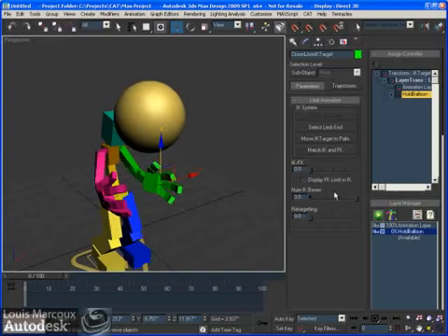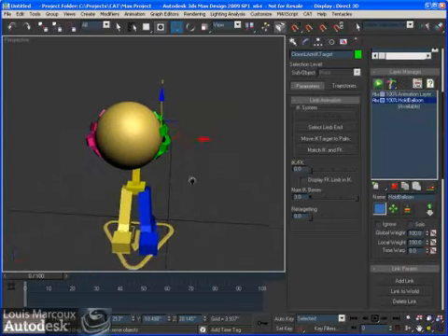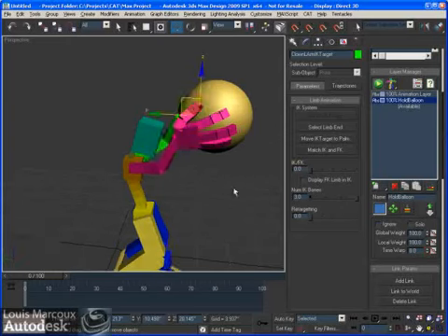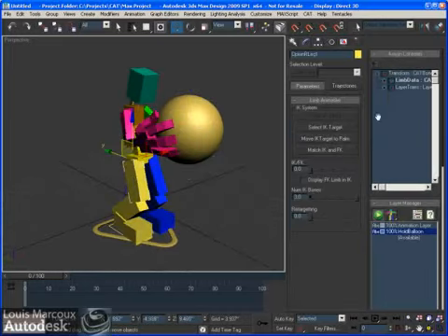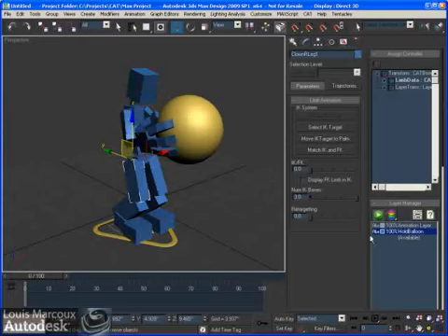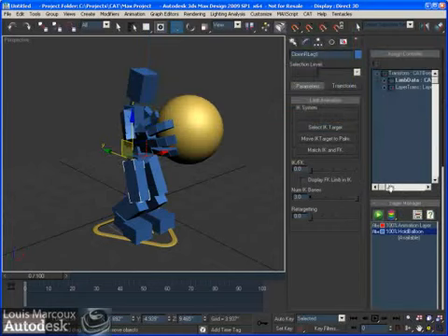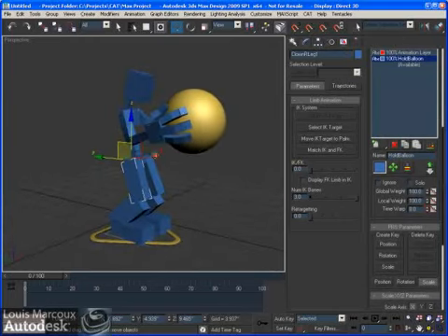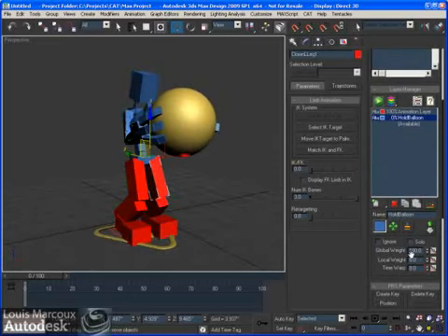So let's go back to full IK here, to the full effect of that layer, because I know that on that layer I'll just be affecting the way that the character hands the balloon. What I could do is grab the whole character, go into animation contribution, select that first layer, and just make it pure red. And the second layer here, we'll leave it to blue, and we'll leave the global weight to 100%, but all of the layers that are not affected by this, I'm just going to put them to 0 so that I can see that this layer is only working on.